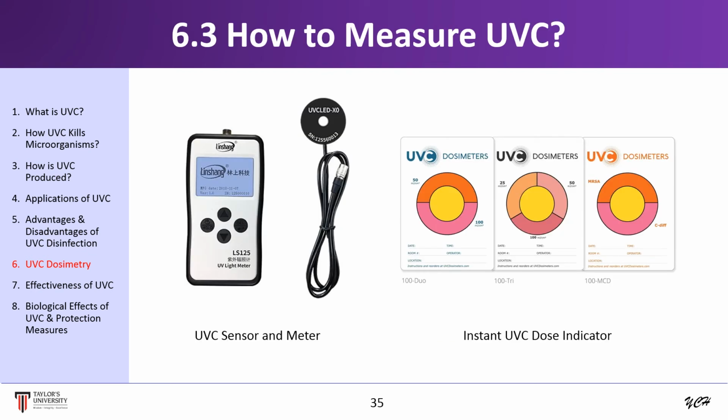So how do we measure UVC? Of course, there's a UVC sensor and a meter, and it needs to be calibrated to the wavelengths of the UVC. And also there are some instant UVC dose indicators available, but these are really very subjective measurements and is not really calibrated.